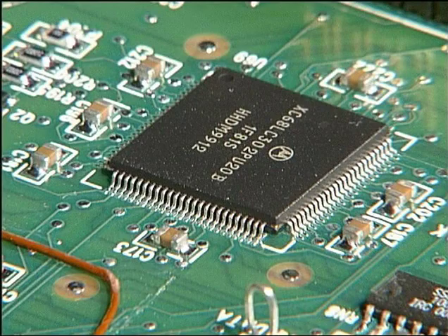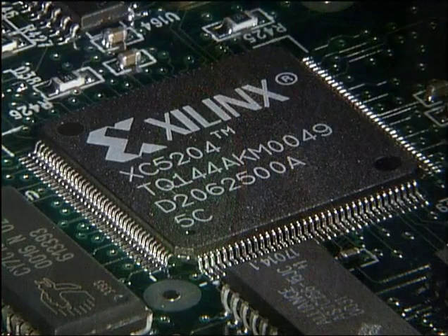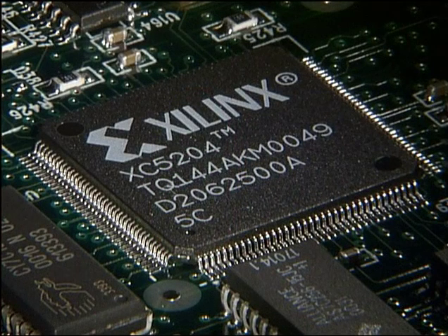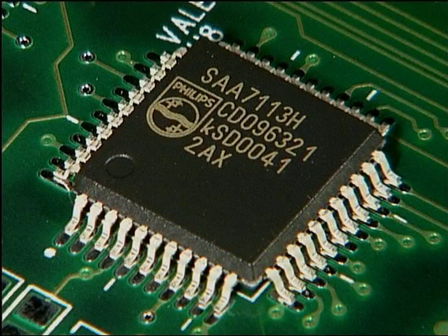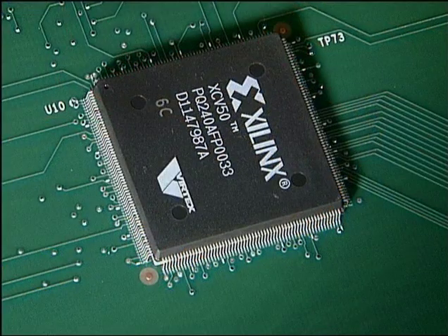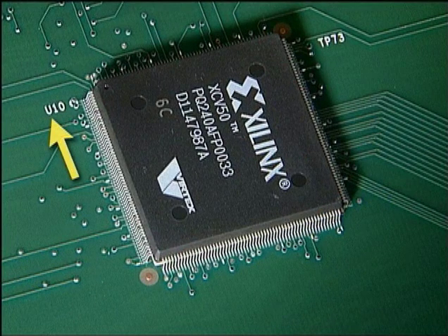The body of a QFP is usually plastic. Their component bodies can also be ceramic or metal. QFPs have gull wing leads on all 4 sides. They can have anywhere from a few to hundreds of leads. The body of the component is usually marked with a part number, date code, place of manufacture, and the logo of the manufacturer. The reference designator for QFPs, like all other surface mount and through-hole ICs, is also indicated by the letter U.